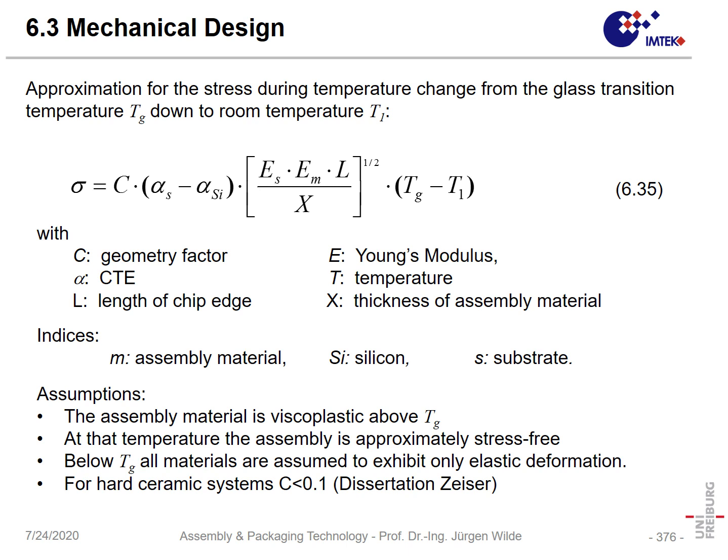Of course, stress is again dependent on delta alpha and dependent on delta T. In our case here again, the Young's moduli and the alpha values are independent from temperature, but the temperature difference, of course, between starting point, which is stress-free, and end point, which has stress, is important. And that here is the effective Young's modulus of the assembly.